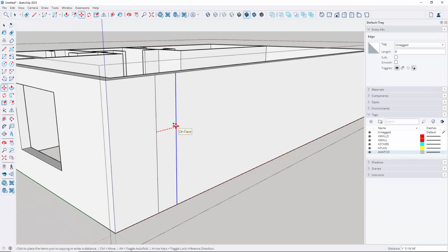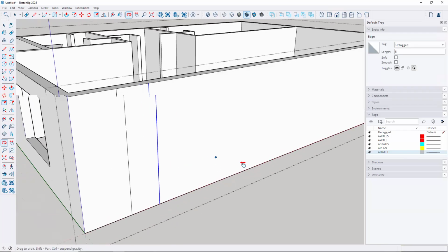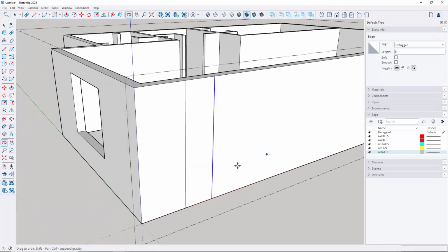And the width on this window, I want it to be 2 feet. So I'm going to type in 2, or I can also type in 24 inches, by the way. So 24, enter. Otherwise, I would have to type in 2 feet and the apostrophe, so that this works. All right. So now by doing that, I've established the width of my building.